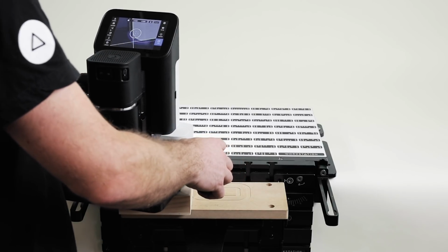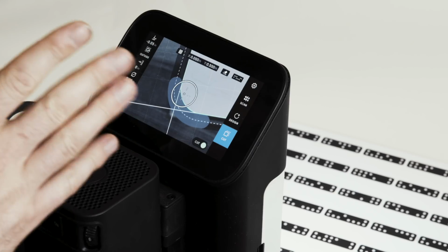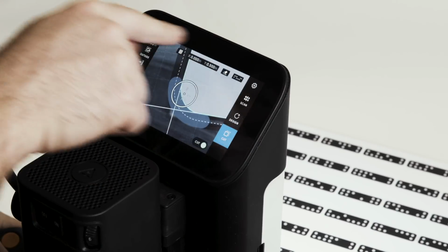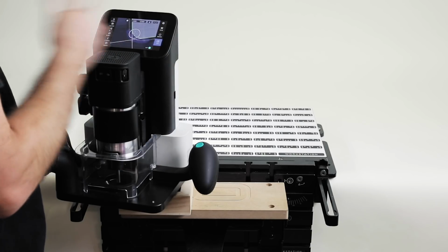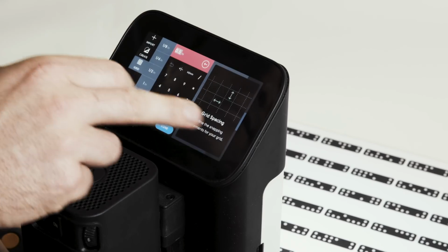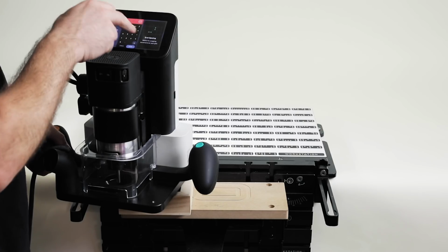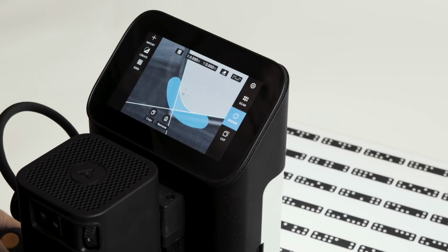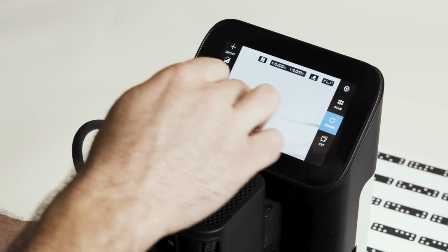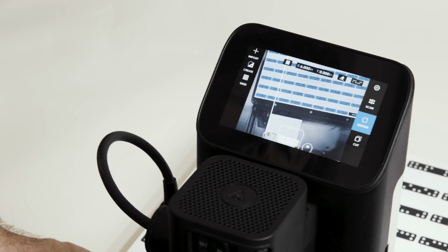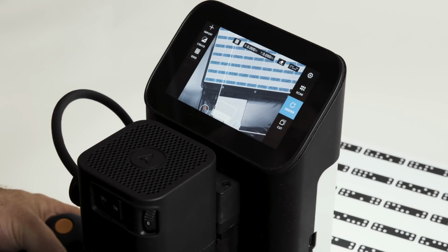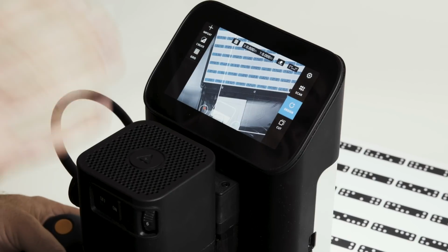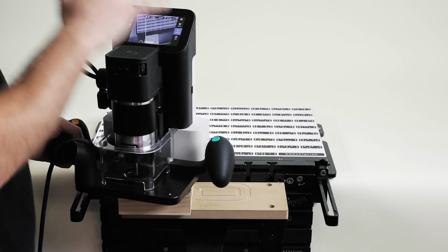The same applies if you're on a floor or something like that. There's a reasonable chance you're not going to want these tiny little grid spacing. So if you're wanting to place things on, say, foot increments, the good news is I can go back here and go modify and set this to 6 inches. And now you'll see, if we zoom out, grid spacing is bigger than this object itself. But that would enable you to very quickly confirm you're aligned to 0, 0 on a large object.